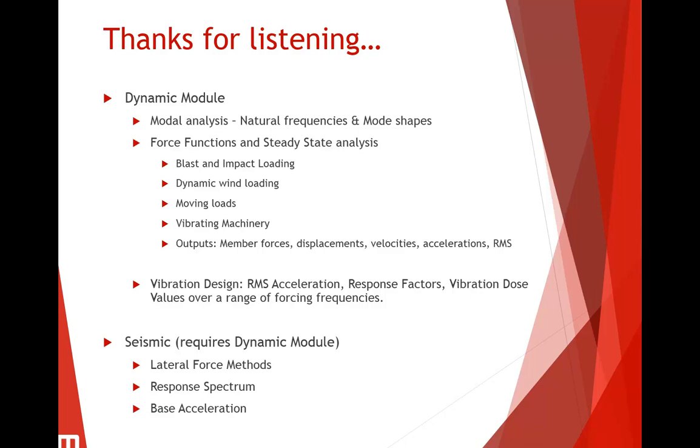And as well as what I showed you, the seismic add-on would allow users to analyze their structure using the lateral force methods, which is a kind of static approximation of seismic forces, or the response spectrum method, which uses the mode shapes to kind of arrive at a good approximation of seismic forces, or the complete base acceleration time history analysis, which is what we looked at just there. And using that, you can then, as per the steady state, output your member forces at critical times during that time history back to MasterFrame, analyze them there, and then design for them in MasterBeam.